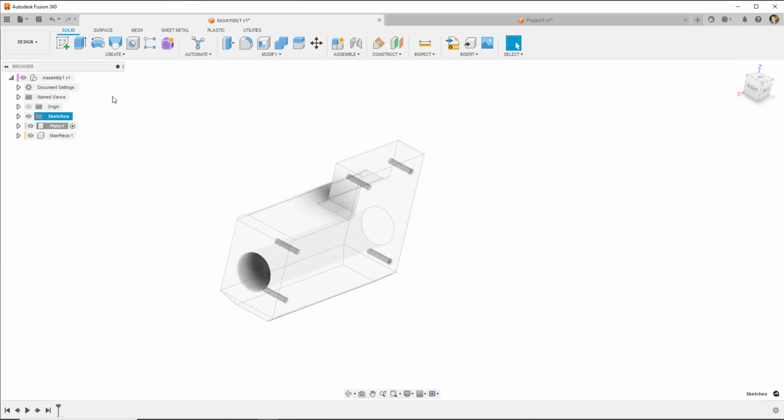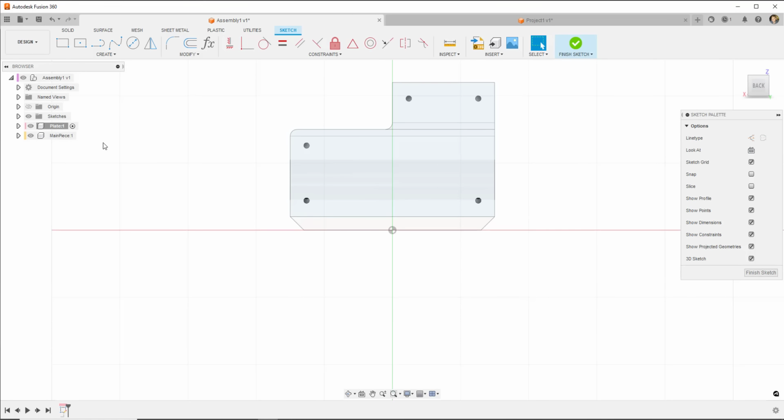And what I could do is I could go back, work out the dimensions, our extrusions, our sketches, and try and create a plate the same size. But we don't need to in Fusion. We've already got it here, so we can use existing geometry where we can. All we need to do, make sure our plate is active. So we're in our new piece. We'll go create a sketch, and I'll select that face. You can select the face even though it's not the active part.